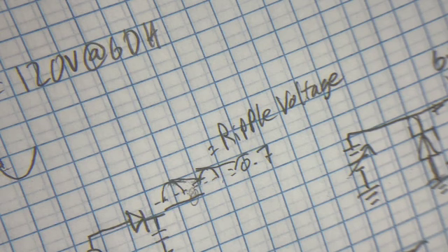He said that if you're using an 8 ohm amplifier and you put a 4 ohm speaker on it, you'll actually get like 1.7 times the power output. And he was justifying what he was saying by pointing at Ohm's law and the power formula of voltage times current equals power.